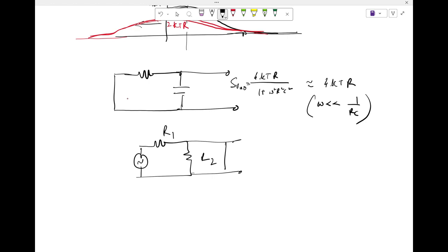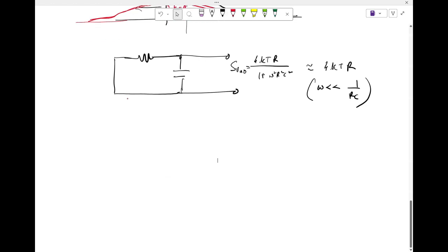Sometimes it can be misleading: you might do a simple noise analysis, and it might appear that the noise is going down, but it might be at the expense of signal. Or sometimes it might appear that the noise is going up, but then you have to go back and check what this does to the signal transfer function. Is it also increasing the signal? So that ratio is important. Only considering noise is not enough, so we'll have to go back and find out the impact on the signal to noise ratio. If I do that for this simple circuit, what should I see?